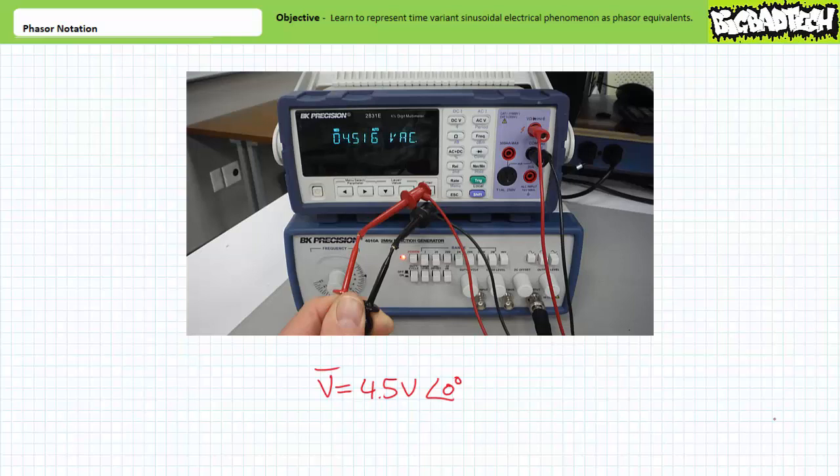What about phase shift? Does a digital multimeter in voltmeter or ammeter mode display phase shift? No, they don't. Voltmeters and ammeters ordinarily do not measure phase shift, but rather restrict themselves to the measurement of effective voltage and current magnitude only. This is to imply that the digital multimeter can only give a user partial information about the true nature of AC circuits. We'll examine the means one uses to experimentally determine phase shift using an oscilloscope in the very near future.